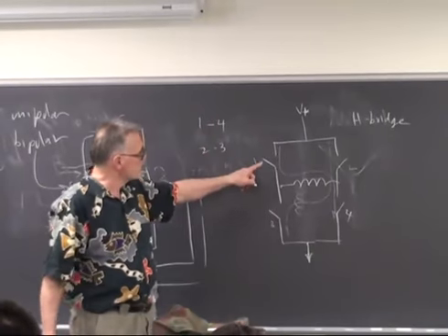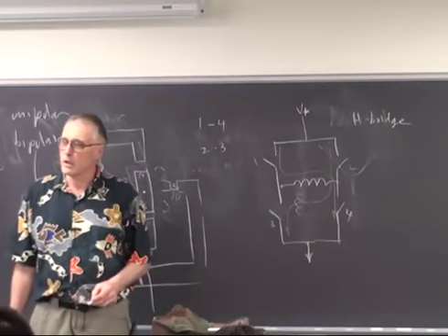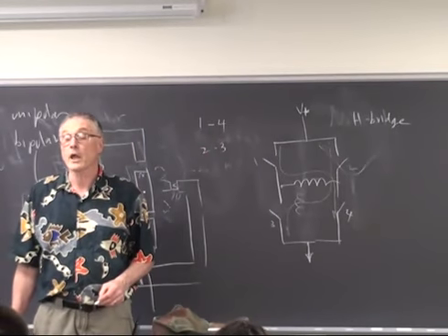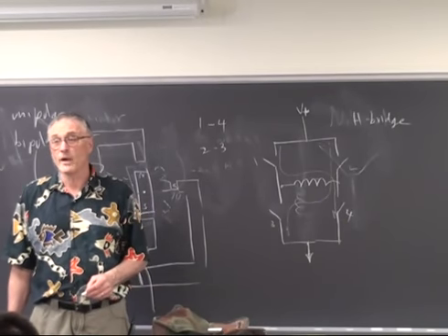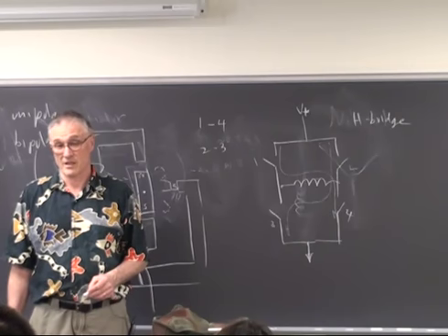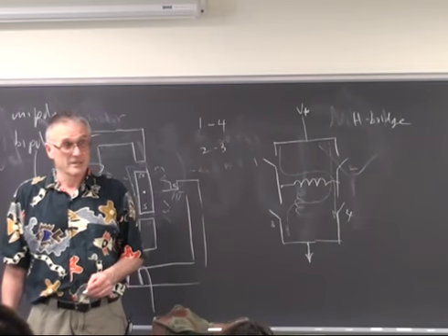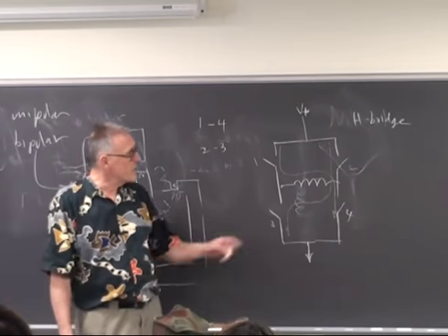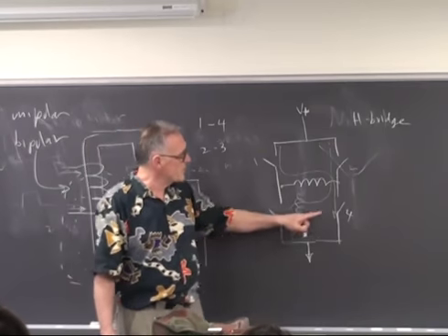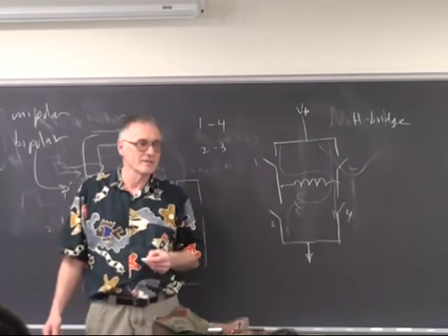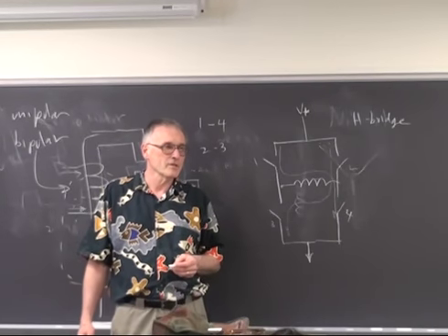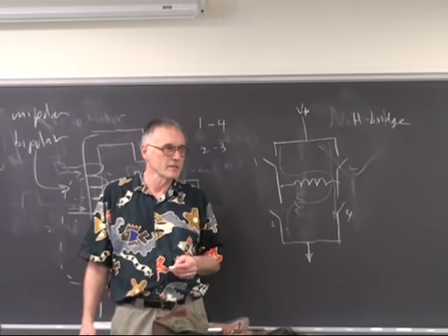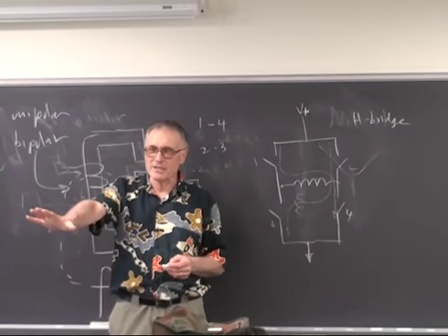If you close switches 1 and 3, you destroy something. All right. I have seen many a whiteboard melt. So, let's say that you were controlling these switches directly off of 4 lines of the CPU. And so software is generating the 4 control signals. Any mess up in the code.